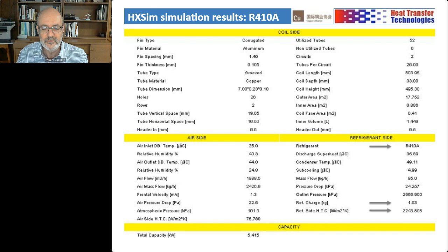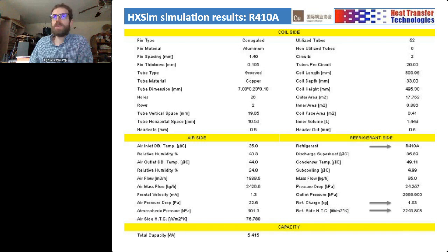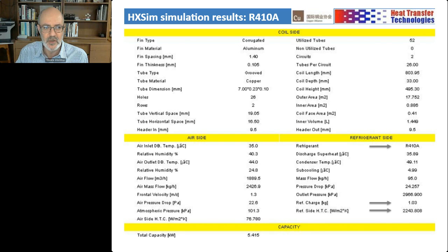Thanks. Phil Jordan is asking, historically, what have been the barriers to incorporating smaller tubes? Is added manufacturing design cost a factor? Initially, when this technology started, it's been going on for about 8 years or so. Could be even 10 in the early stages. The difficulty was actually to get equipment, to get hairpin benders, tube expanders, tools for fins, making fins with 5mm holes and the respective collars. And those issues are over. There are many companies that supply equipment to make 5mm tubes.